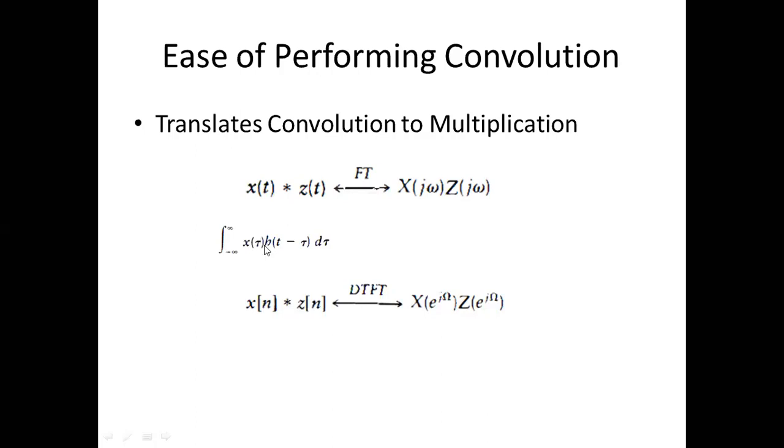So instead of shift, multiply, summation, if you take the Fourier transform of x of t, say X of omega, and the Fourier transform of h of t, then convolution just becomes multiplication. So instead of multiplication, shift and integration, or multiplication, shift and summation, you can manage with only multiplication, right?